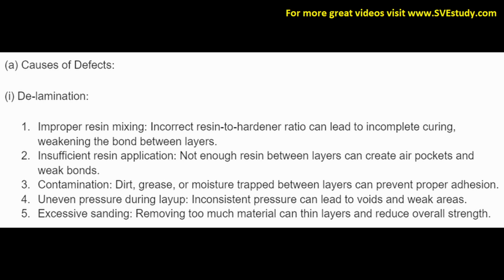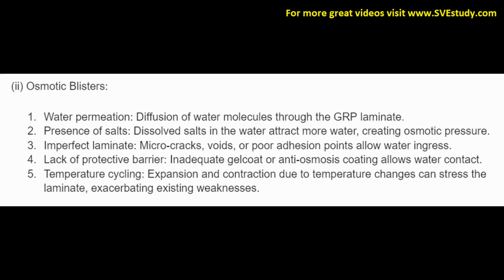3. Contamination. Dirt, grease or moisture trapped between layers can prevent proper adhesion. 4. Uneven pressure during layup. Inconsistent pressure can lead to voids and weak areas. 5. Excessive sanding. Removing too much material can thin layers and reduce overall strength.